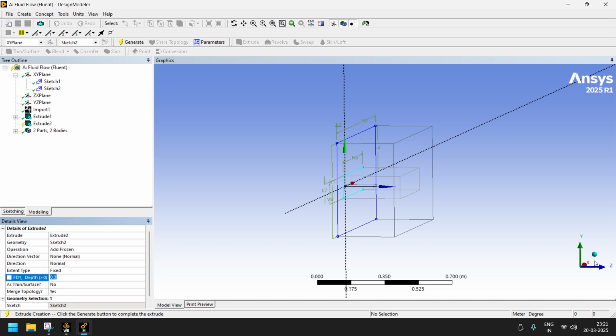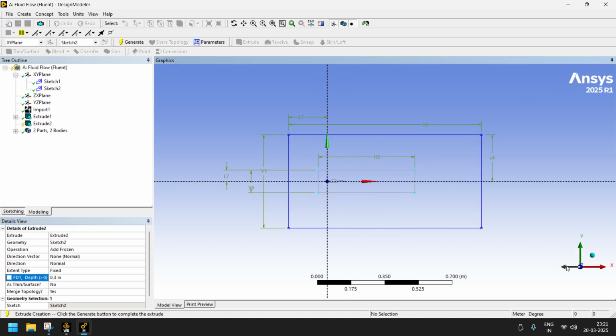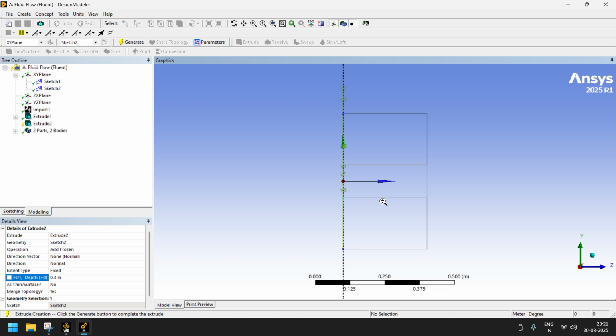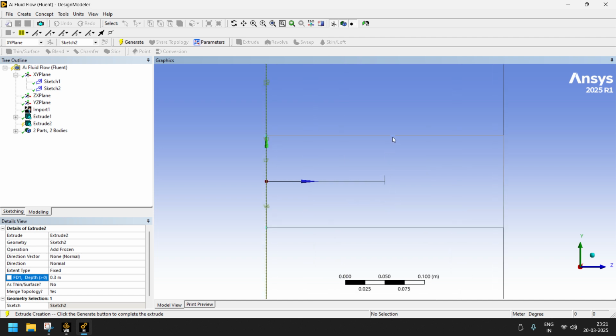And this time again go to the side view. So I am going to create from the tip to some small distance. For example, 0.15 means I can give 0.16, so that the small box is just covering the wing. Here alone I will get the very fine meshes. So 0.16 or 0.175, like that, depends upon the model you can decide. Just I will go with this length. So now you generate.